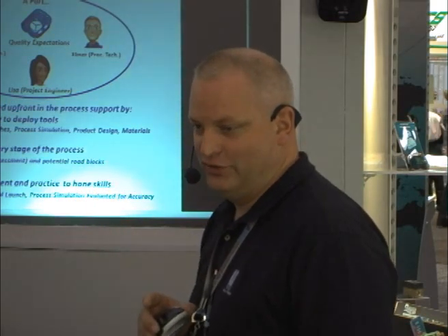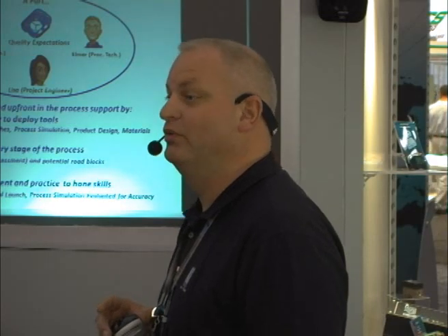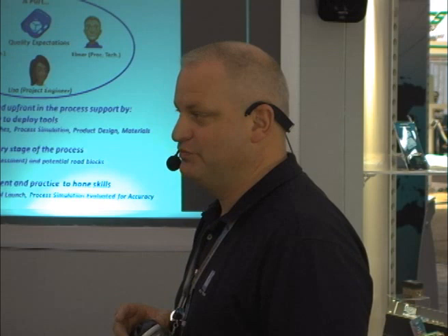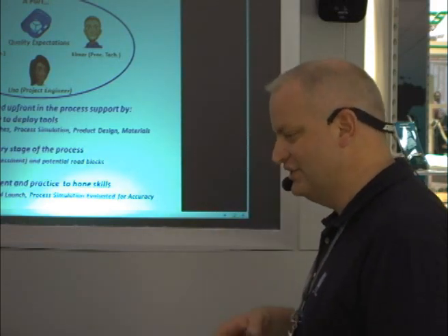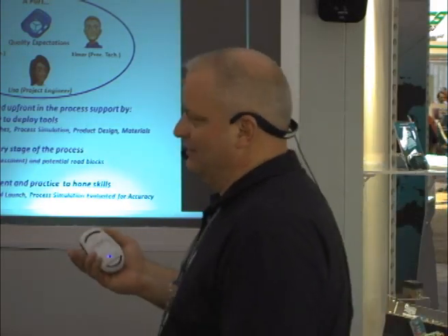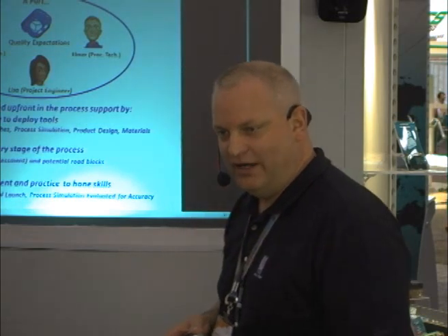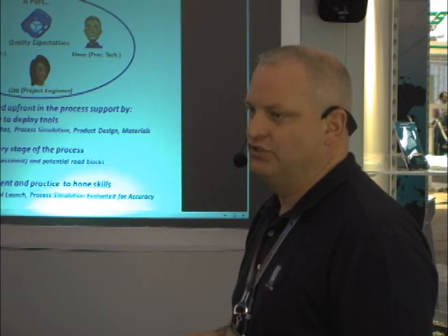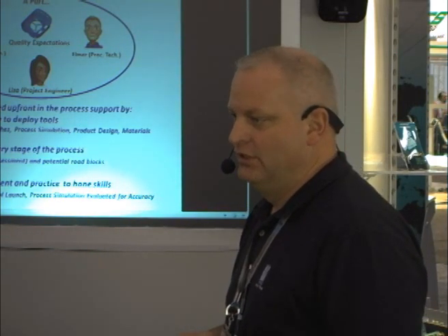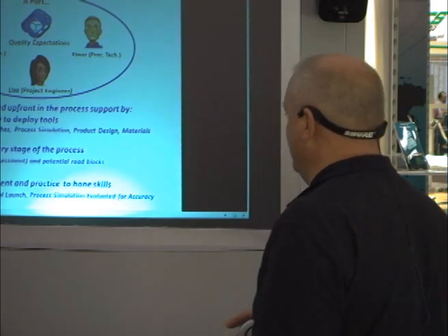The first trial, we weren't successful on developing an instrumented process because the tool wasn't functional and the ejectors actually hung up and stuck and did some things. But at that point, we didn't take the approach that we're going to continue to try to run it without things working correctly. We actually sent the tool back to the tool shop. They sent it back within about 12 hours, and then we put the process in off the process simulation and matched the process simulation at about 92%, which was pretty impressive.